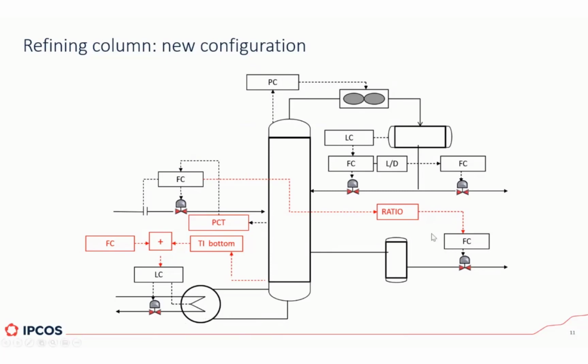And then as well, since to guarantee that you're taking most of your impurities out, then the flow controller that is attached to this side stream is in fact in ratio with the feed, meaning that if the feed changes, then this immediately changes to accommodate for that.